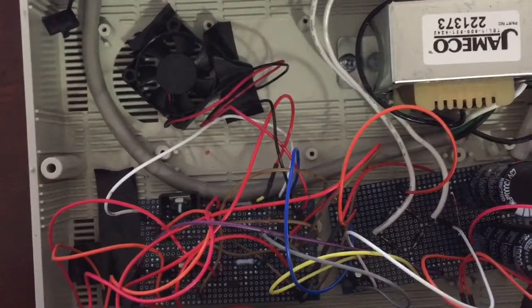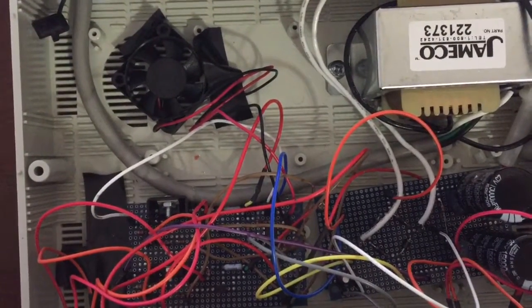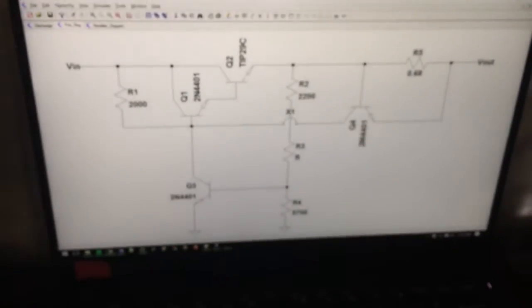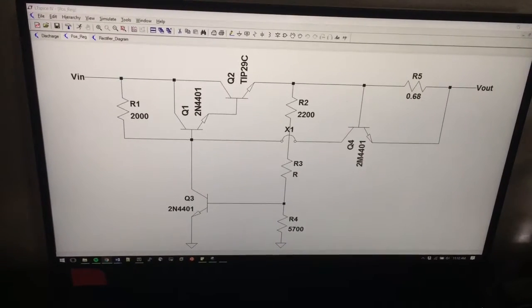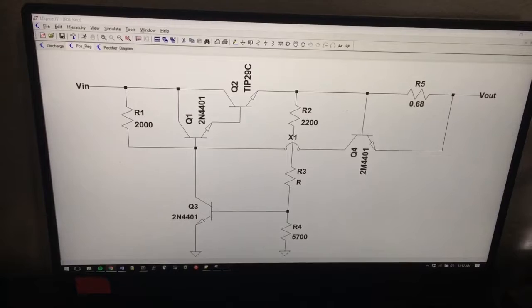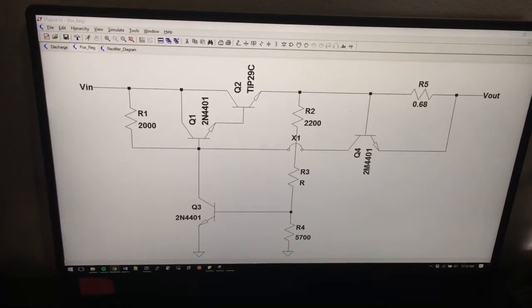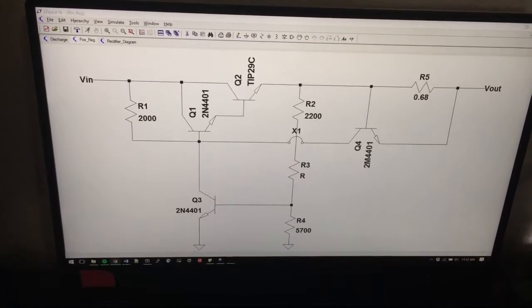Next, I will be demonstrating the use of BJTs within this circuit. So you might be able to see them here. Unfortunately, it's a little unclear with all the jumper wire, but this heat-sinked BJT, and maybe you can see all these other darker BJTs, but this subcircuit is a voltage regulator. You can see a schematic here. The purpose of this circuit was to basically set the output voltage and maintain that, and do some current limiting to protect some of these components.